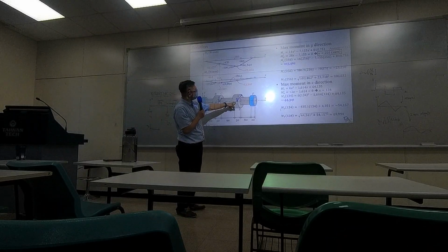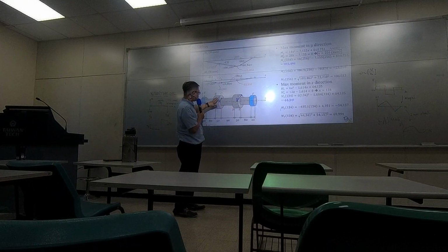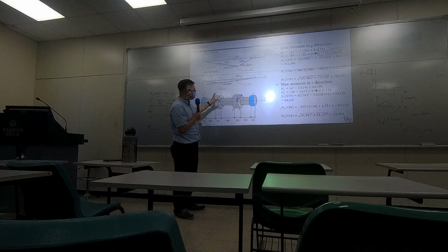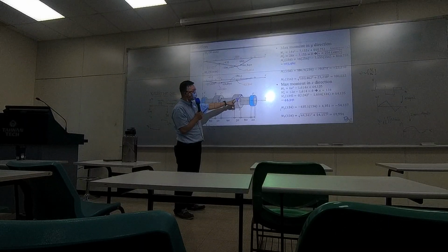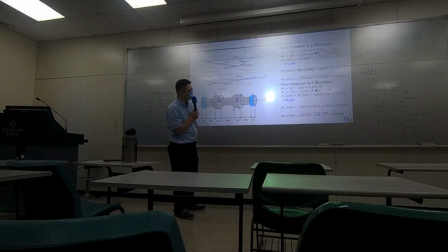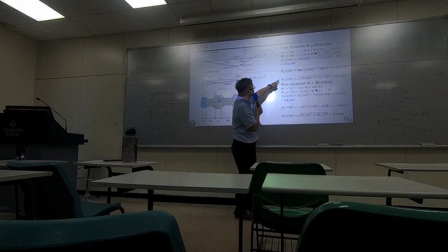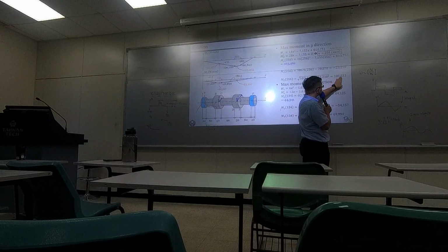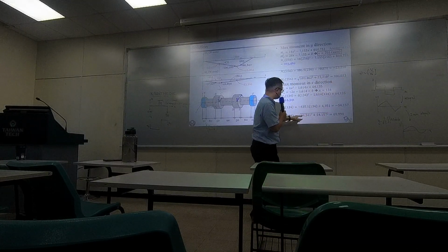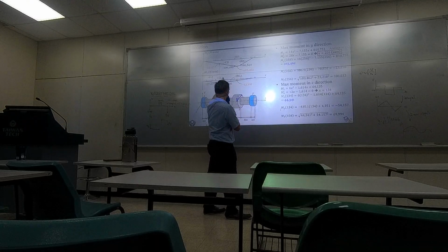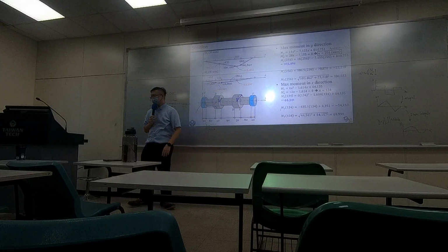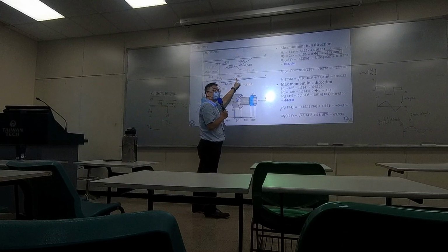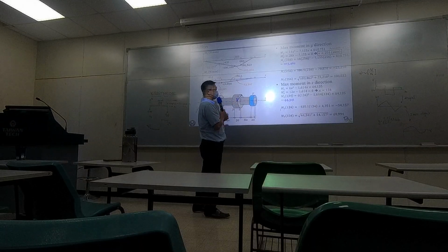I think I remember this one is larger. I may screw up some of the vector direction. I remember I made some mistake in the previous slide, but you got the point. You basically need to figure out which position has the largest M total. This one at 256 has 106033, larger than the total moment at the position of 134. So this is the critical position. If the beam is going to fail, this is the position.